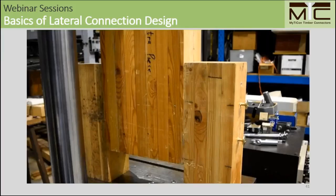In order to show this on a live video, I want to look at this little video and explain that in the beginning. You can see 2 fasteners installed in the side member of this H-block test here. The heads are a little bit left out of the side member, and the thread of this fastener, so it's a partially threaded fastener, is completely embedded in the main member. So there's no axial resistance in the side member at all.